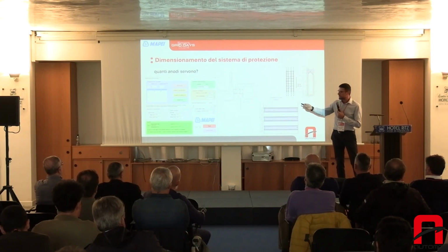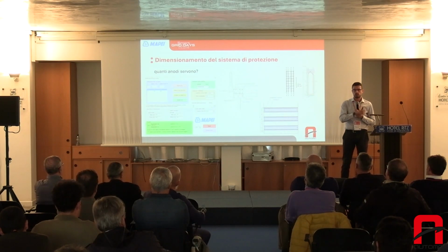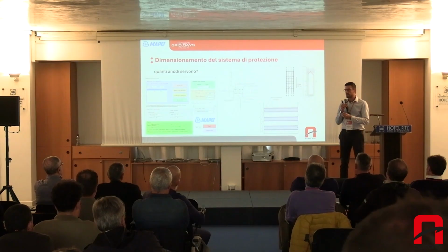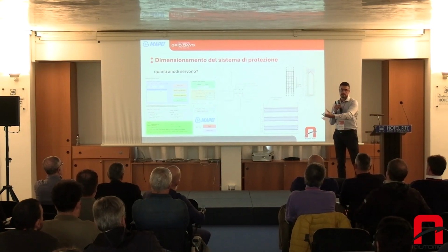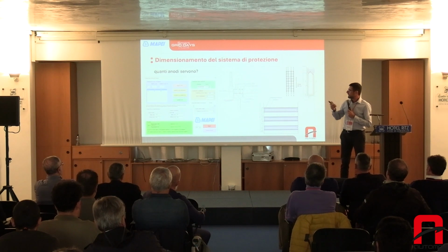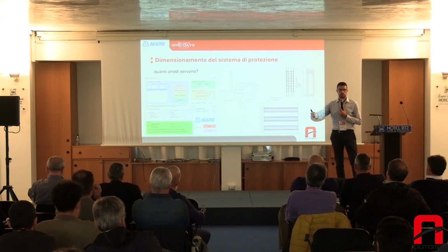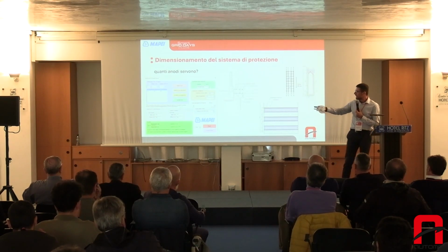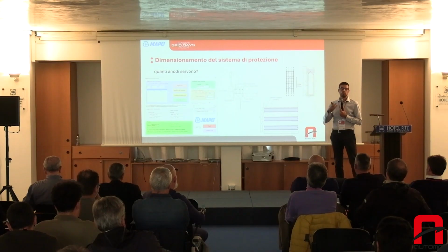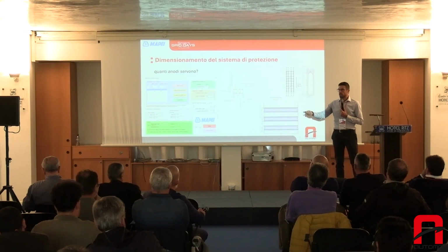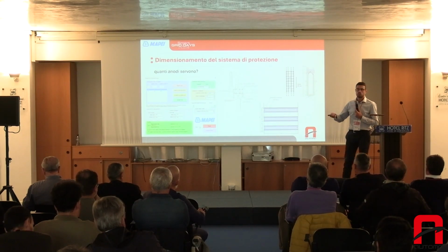So, depending on a series of parameters, it's a new structure or an old one. If it's a new one, what is the exposure class for this structure? In this case, we can collect several pieces of information, so we can understand what's the amount of chlorides in the environment, what is the average temperature, the duration for this protection system. Based on these parameters, the program provides you with the number of anodes and the spacing between them to be able to protect the structure.